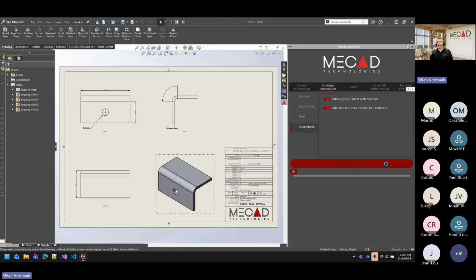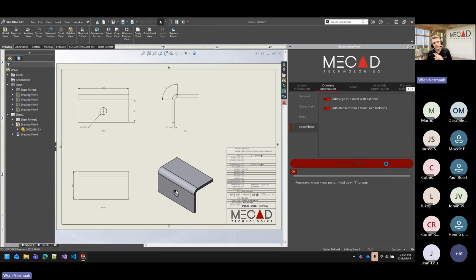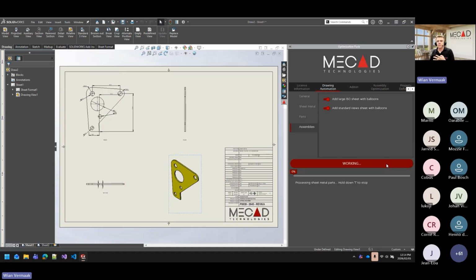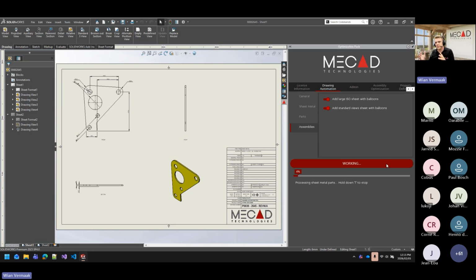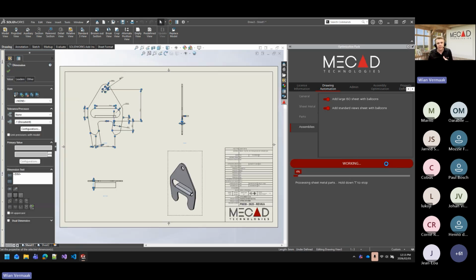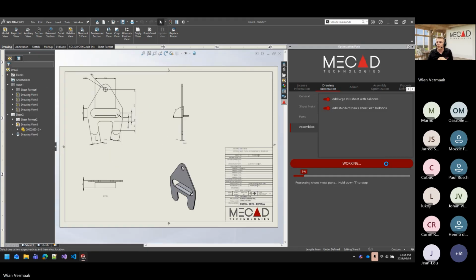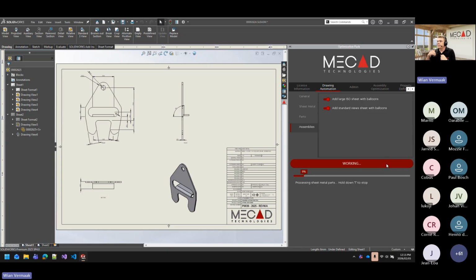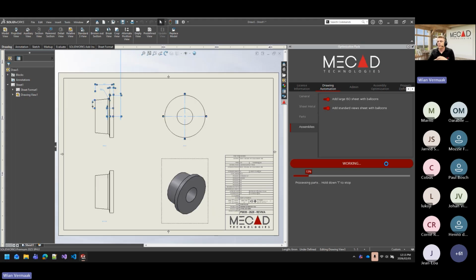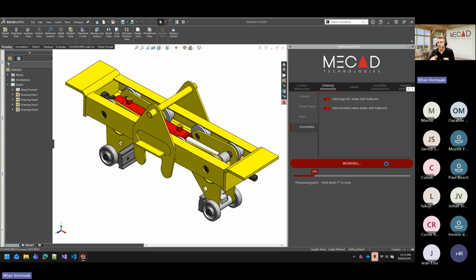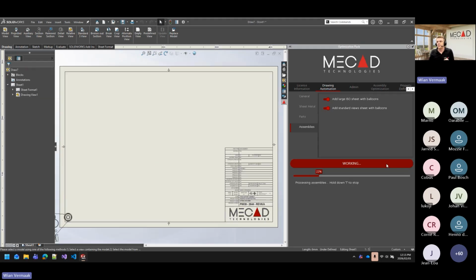The moment I click play, it's going to scan the entire assembly for sheet metal, standard parts, and assemblies, and categorize them. This one starts with the sheet metal parts, creates a flat pattern view, annotates the bends, creates the bend lines, all of that fancy stuff, as well as the standard views. Then it'll move over to the standard parts, the normal ones, in this case a weldment. It creates hole callouts, surface finishing, and weld symbols. It really goes the full nine yards.